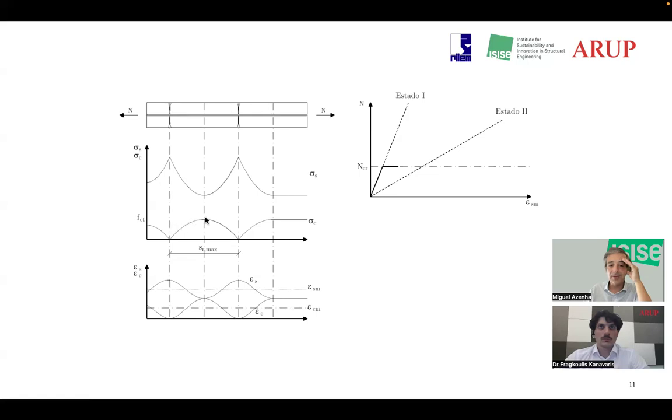This means that the stress in concrete cannot reach enough state to generate another crack. So this is the maximum crack spacing. And then to the left, there's no way we can get a new crack because the stress will not be able to increase. And only we can get a new crack on this right-hand side. And this is exactly what happens. A new crack will happen somewhere there.